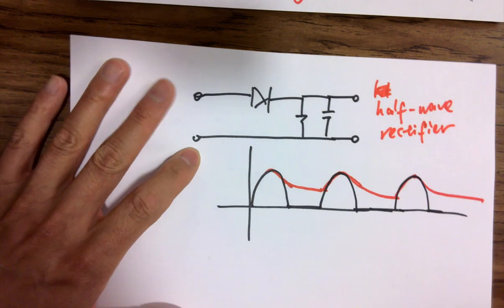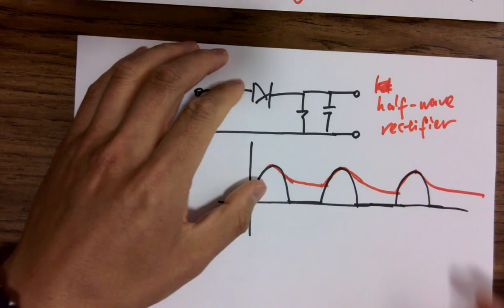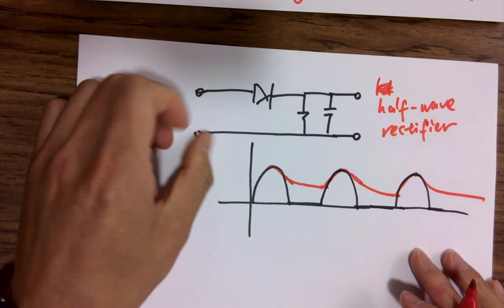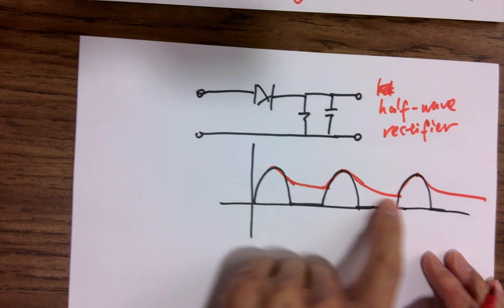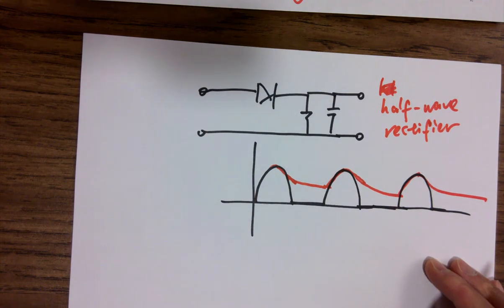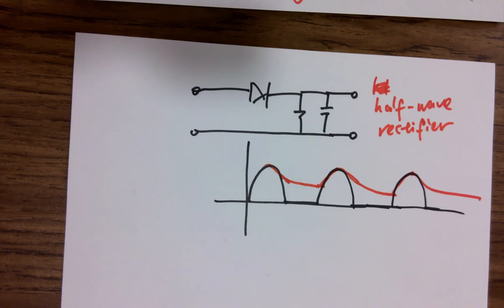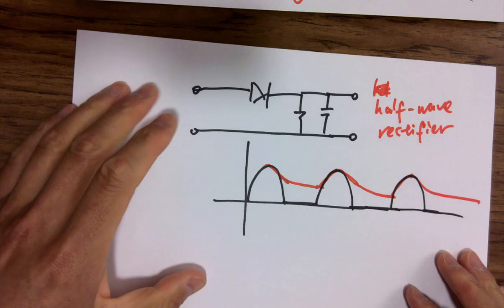Rectifier, right? It's being used for transformers. So you got transformer output. Use a half wave rectifier. It can convert the AC signal into DC, right? And then do a regulator after it to stabilize it to your digital voltage level, like 5 volts or something, right? If you have a full wave rectifier, we're not going to cover that.